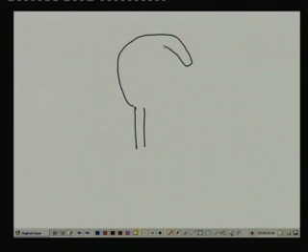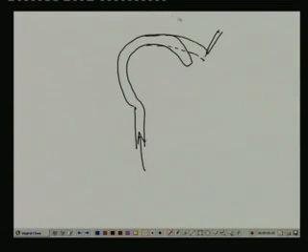Suppose you have studied the Bourdon tube. See, the tip looks like this, is it not? If the pressure increases, we have seen that this tip moves like this. With some arrangement we have connected it to the needle, or pointer, and that dial is calibrated in terms of pressure. Here you see this movement I can put on a shutter, is it not? So light is coming in and light is coming out with the collimator lens and all these things. Light is coming parallel like this, then again it is coming to the other fiber, right.